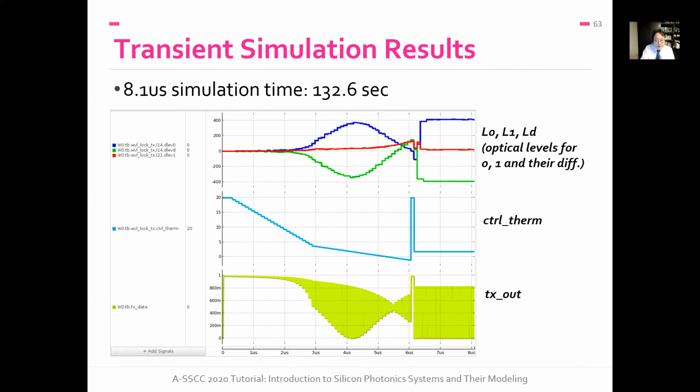You can see that as you sweep the temperature, the separation gradually changes, and at some point you hit the maximum, and then the separation gets smaller again. You record all these results, and remember where you got the peak separation. So when the sweeping is done, you select the temperature that gave you the largest separation and start using it. And after that, you can start sending real data.